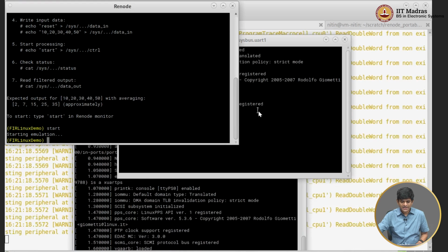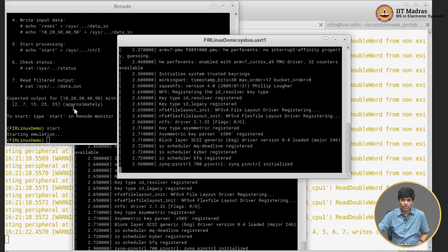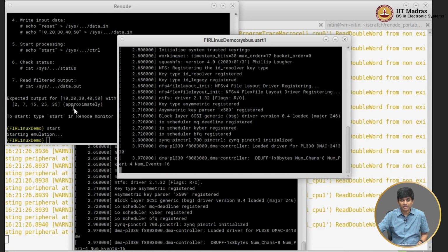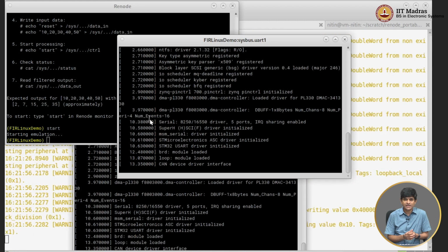So currently what I am doing is running the same Renode emulation, but now with the frequency for the co-simulation set at 10 megahertz, right, and you can notice that it is now running appreciably slower. It is definitely far slower than when the frequency was set to a lower number, and the basic reason is that the number of times that the co-simulation gets activated and needs to run is much higher, because the relationship between the Renode internal frequency and the simulation frequency of the system are now much closer.